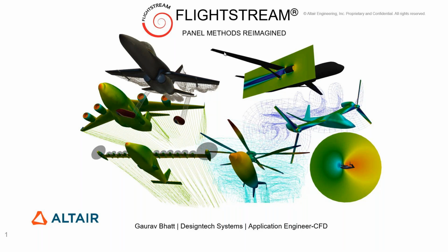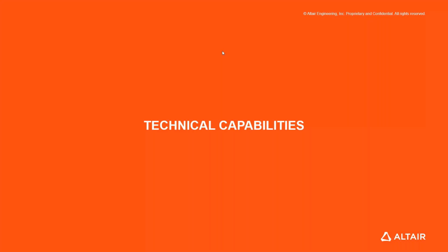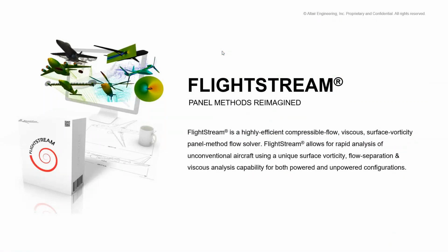Coming directly to the technical capabilities of FlightStream, it is essentially a panel method flow software. Some of you who work in aerospace and defense may have heard of the phrase and maybe used it in the past. Before the tool was acquired by Altair, Research in Flight worked heavily on research and rewrote the panel method formulation to make it much more efficient, able to handle compressible flow very nicely, have full viscous coupling, and get rid of some of the limitations associated with the older panel methods.